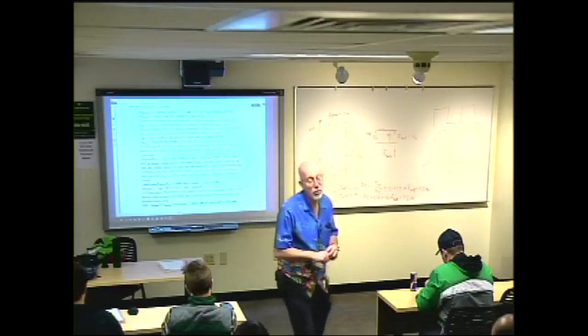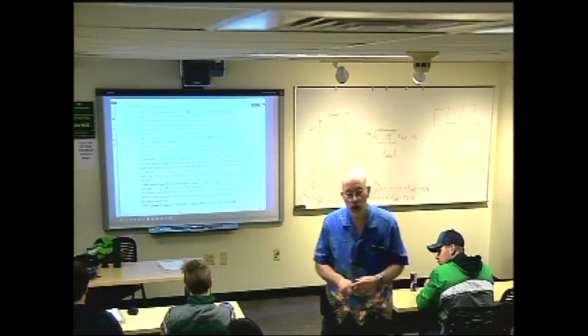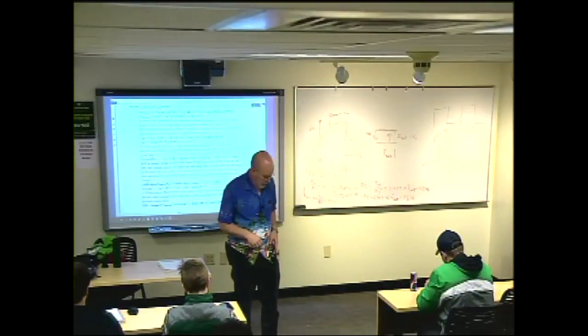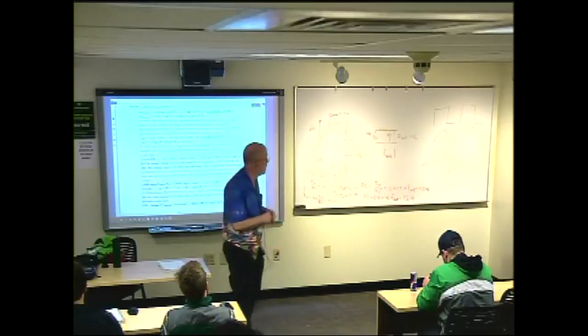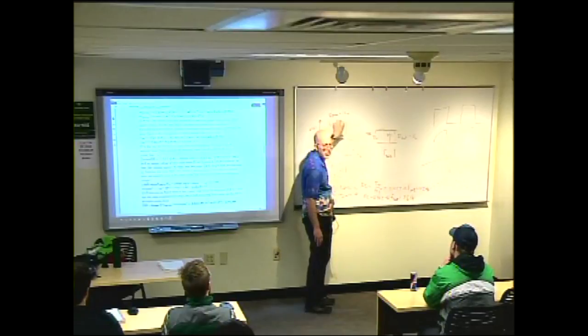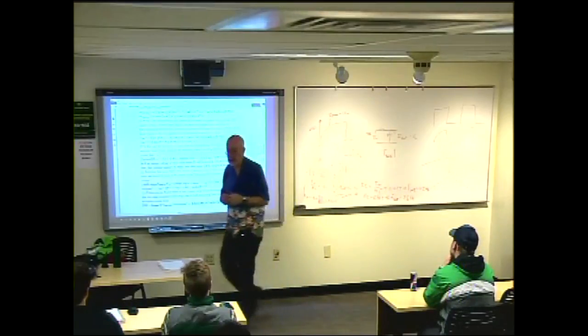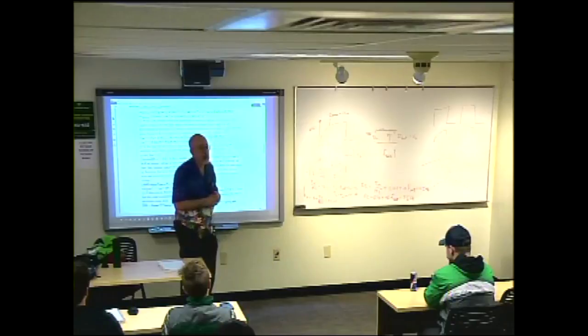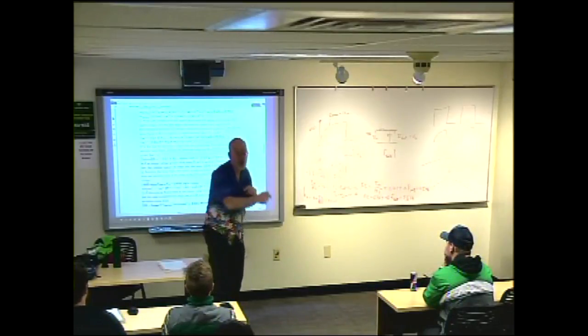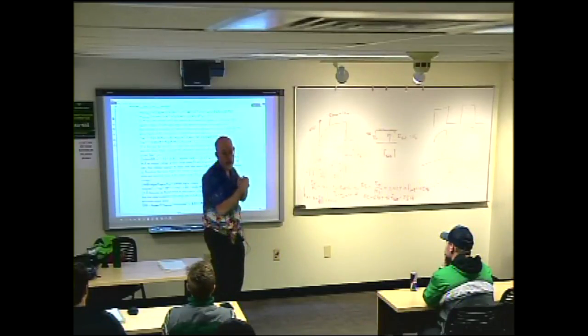The SNR would be proportional to what? The RC time constant. In that case, that would be. You're right. You'd have a different noise level for falling than you would have for rising, and in terms of analysis, you'd have different signal to noise ratios. The only thing I would say about what you said is signal to noise ratio is actually inversely proportional to RC. It's not proportional to RC. Oh, wait, it is. I'm sorry, you're absolutely right. Signal to noise ratio is proportional to RC.